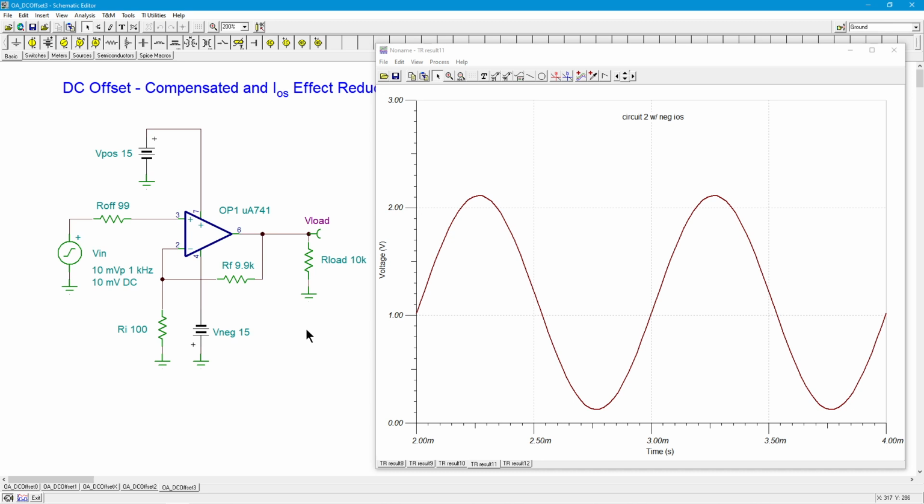All right. As a matter of fact, to compare amplifiers on an even keel, what we sometimes do is compute what's called input referred offset. We take the output offset voltage and divide it by the signal gain of the amplifier. That way, the value that we get, we can compare from amplifier to amplifier if those amplifiers have different gains. All right. So that's an even way to do it. Otherwise, high gain circuits always appear to be worse just because the gain is so high.